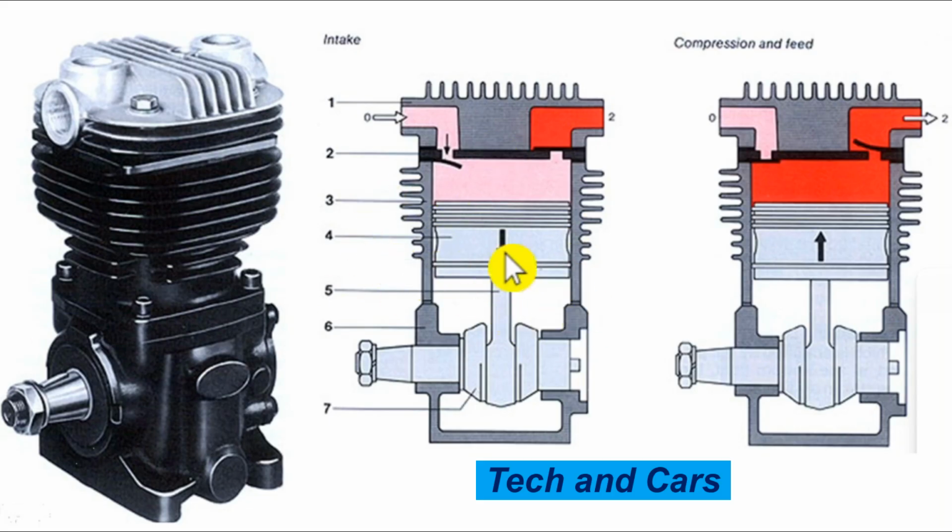The other thing that can happen is if the compressor is not building any pressure at all. This is an indication of a severe air leak, a major line or hose disconnect or burst that can cause totally zero pressure to build up. And a broken compressor drive. This drive, the crankshaft or the pulley that is going to drive, if there is some discontinuity there, then there will be zero pressure. And if the unloader valve is stuck fully open, that will also prevent pressure buildup. That will prevent compression in here. So that will cause zero pressure discharge as well.